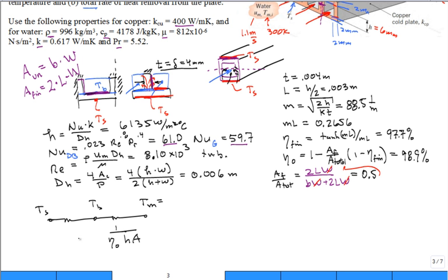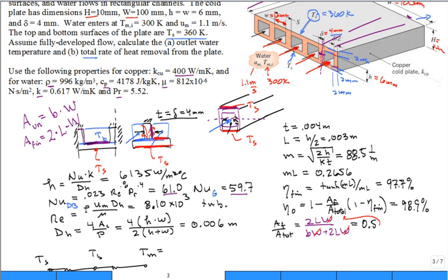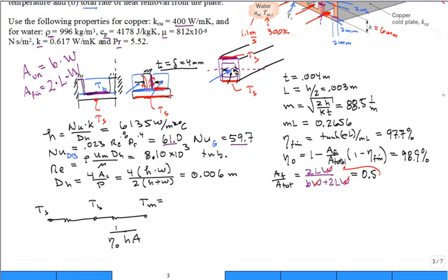Okay, and this is just a thickness of the copper. I used that symbol already. That thickness, if I look at my illustration, is going to be delta over 2. It's 2 millimeters. I'm trying to find other symbols here. Let's call it delta of the bottom, which is 2 millimeters, divided by thermal conductivity of the copper, and we have an area.